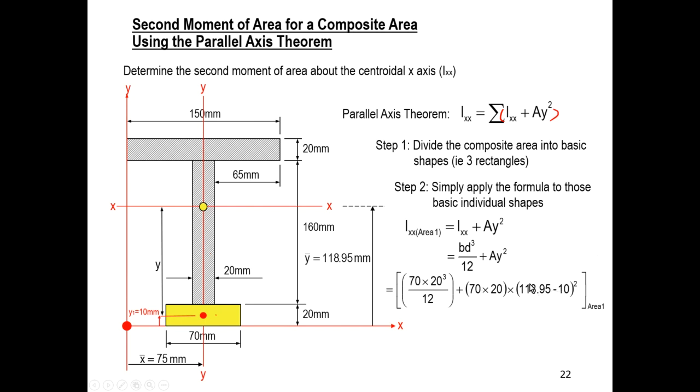This is the penalty. This one you get from the table, it is a standard value. That penalty added to this one is the moment of inertia of the yellow with respect to the centroid of the compound shape. So this one we finished.